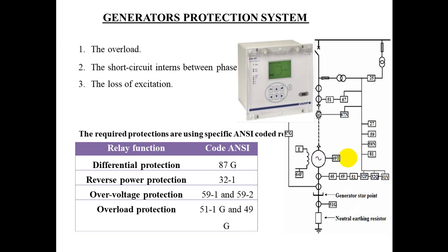Reverse power relay is used for the purpose. Reverse power protection relays, as shown in these pictures, are also called 32P or 32 protection. As soon as the generator starts rotating in motoring mode, the reverse power relay will trip the generator set.